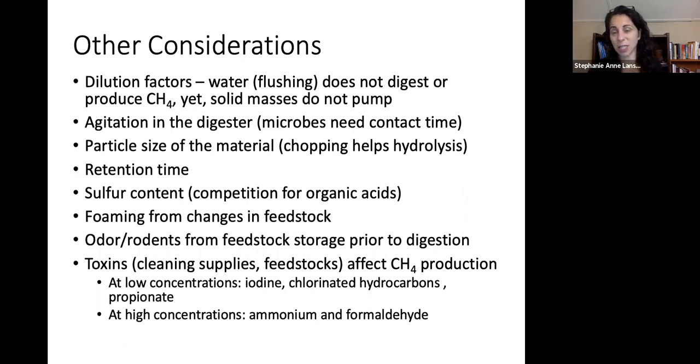Again, the agitation and the particle size. We can use a chopping pump that we can put in there so we can break up the particle size before it goes into the digester, and that'll help reduce some of the time needed for hydrolysis.